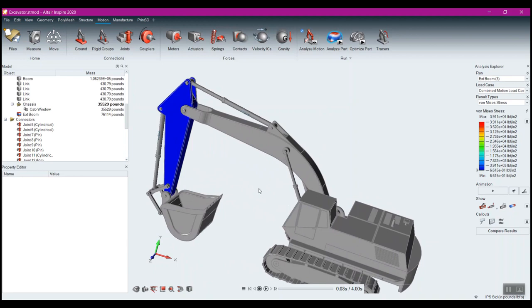I added no loads, no constraints, nothing other than to run the motion analysis first, and you do have to have a completed motion analysis, and then simply click the little run icon, select the part you want to go, and you'll very easily get a structural analysis. So hopefully you can get some even more useful results out of your motion analysis. And in the next video, we'll talk about doing the same thing, but allowing us now to optimize our parts from that motion analysis.